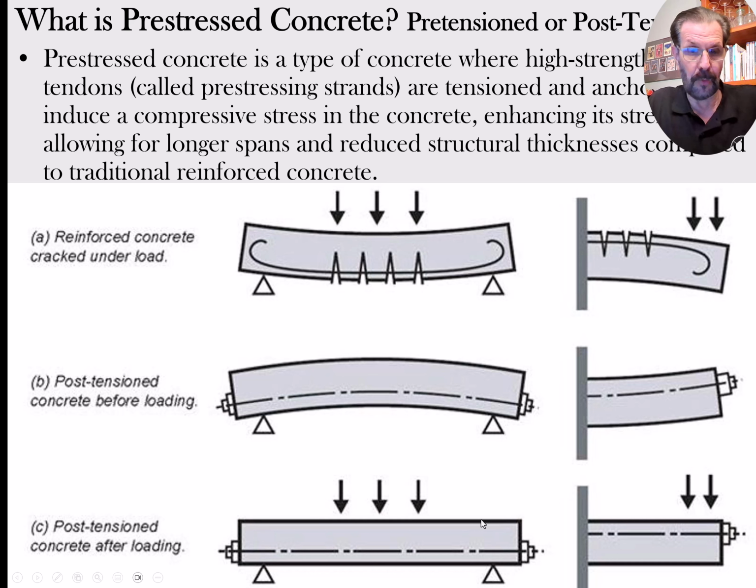And so that's the whole calculation of how much tension you want, how many pre-stressing strands, and all of that. Anyway, so the act of having steel that's already under tension, that means it's already actively holding the particles together in the bottom of the beam before there's even a load.